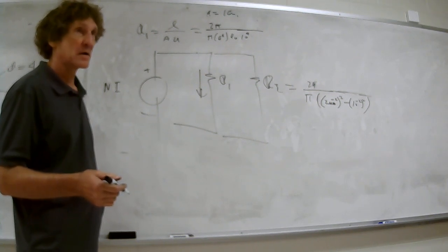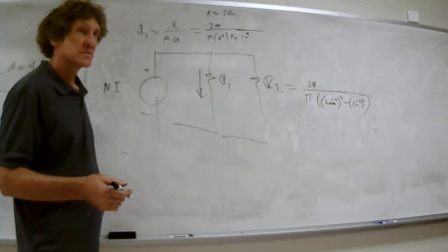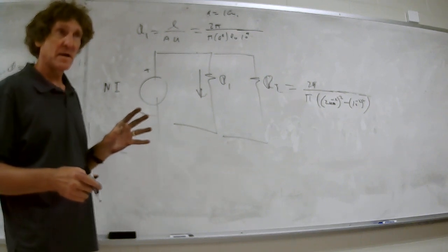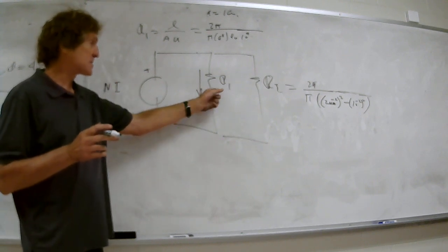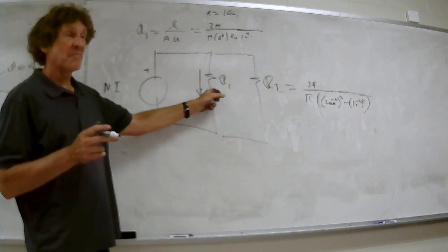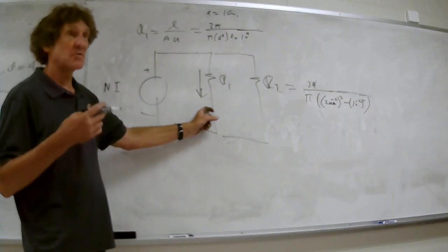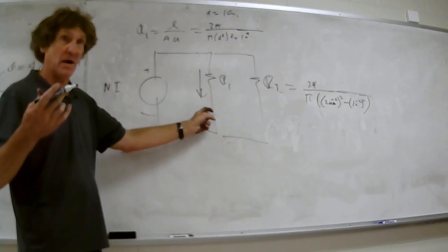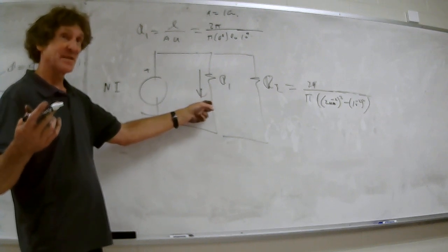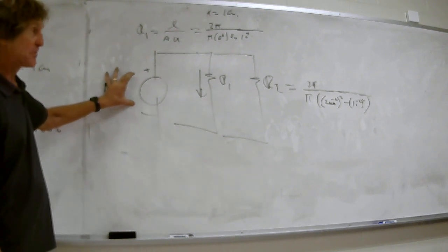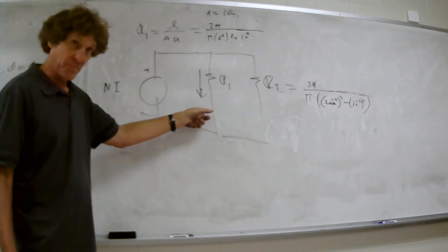That's no problem. Now look, I want to show you this. Do y'all agree? Just hear me. If I want the magnetic field intensity in the inner core, if I find the total flux in the inner core and divide it by the area of the inner core, I would get the B field, right? Yes. Right? So how much flux is in there? This is like a voltage. It would be Ni divided by reluctance 1.